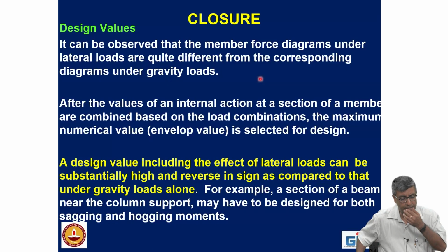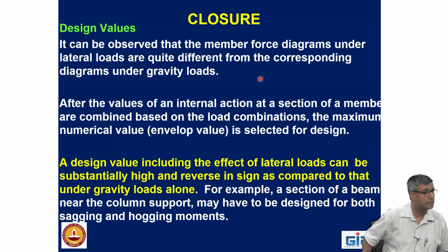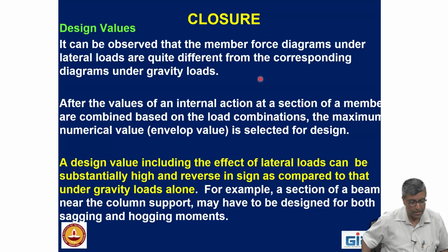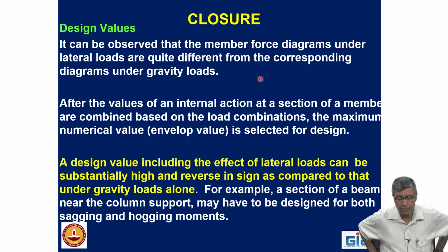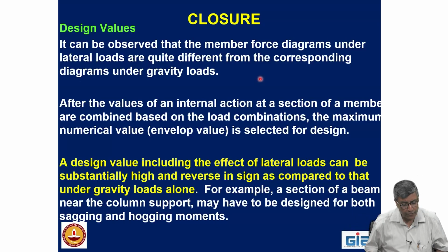Closure. Let me read it out. This is important, because a full 1 semester course I finished in 1 hour, right? It can be observed that the member force diagrams under lateral loads are quite different from the corresponding diagrams under gravity loads. That we have to appreciate, that these are two different ball games. After the values of an internal action at a section of a member are combined based on the load combinations, the maximum numeric value from the envelope is selected for design.